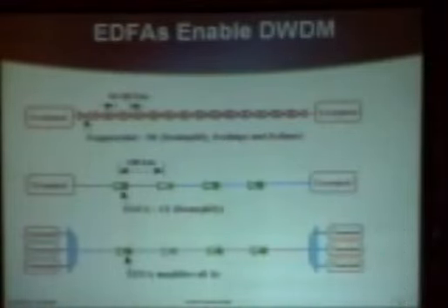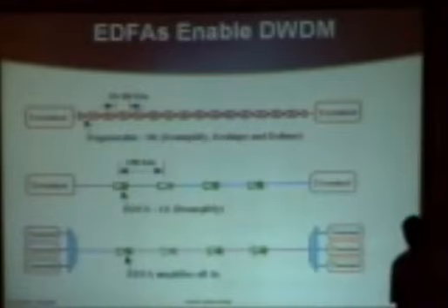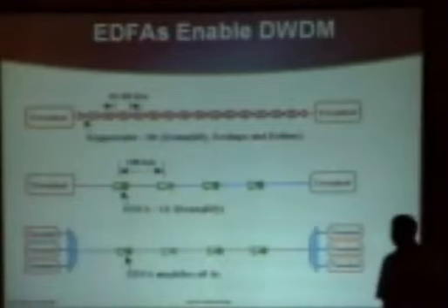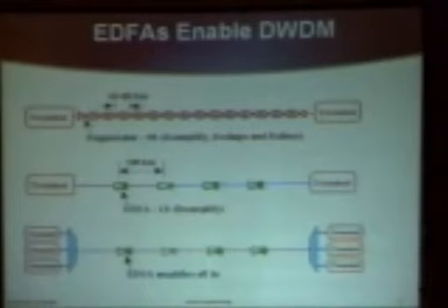Well, to give it a historical perspective, we wouldn't be talking about WDM if we hadn't come along with an optical amplifier in the earlier days. Around mid-90 to 95, somewhere in there, depending on who you ask, optical amplifiers became commercial. And the king of the optical amplifier is the erbium-doped fiber amplifier, known as the EDFA.